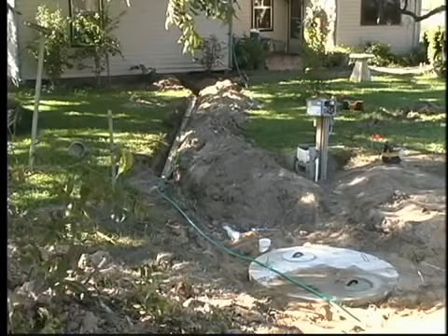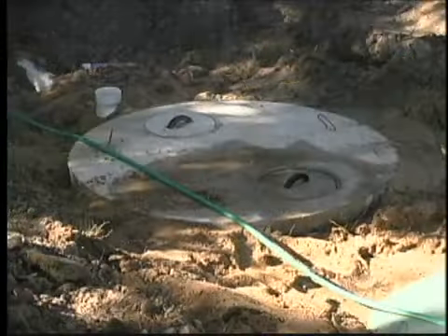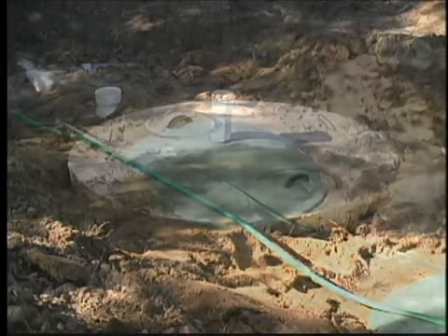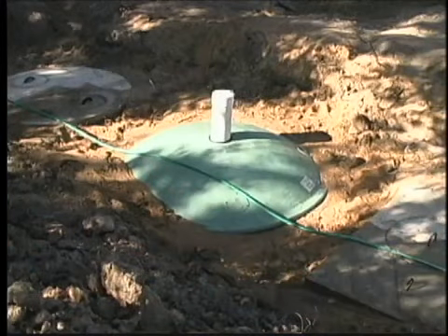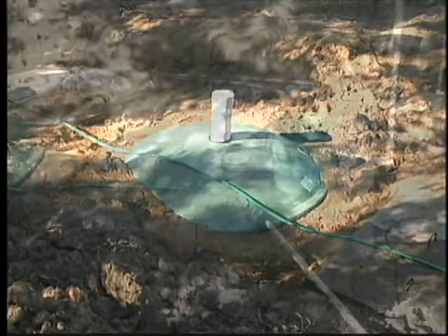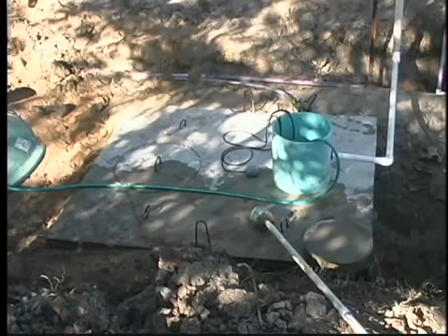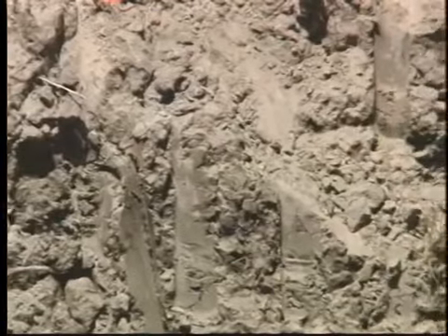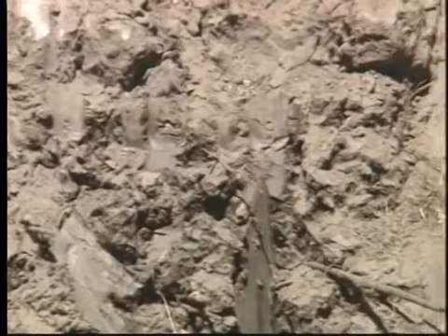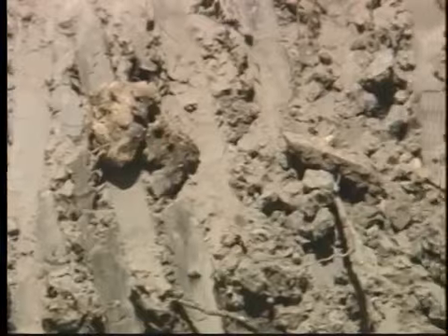The treatment tanks should not be placed in a low area where rainwater will collect and flood the system. Watertight risers should be placed on top of the treatment tanks to allow access to the tanks and prevent rainwater from entering the system. The soil should be evaluated across the site. Soil profiles can be consistent across a given tract of land or can vary greatly within just a few feet.